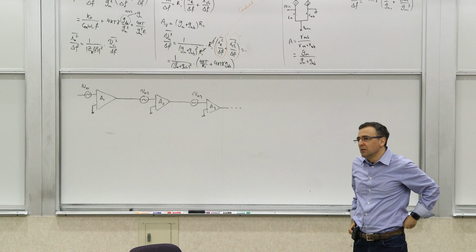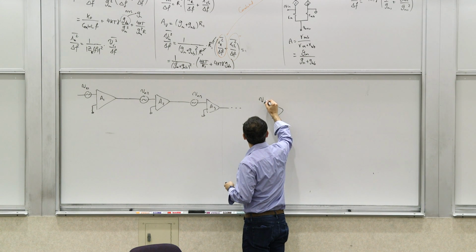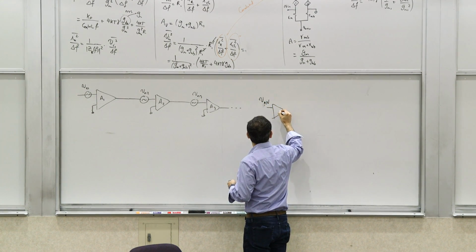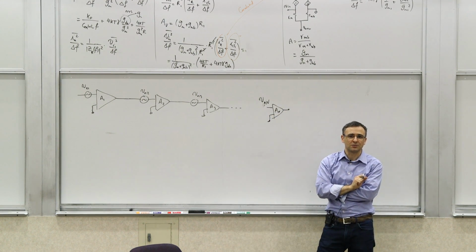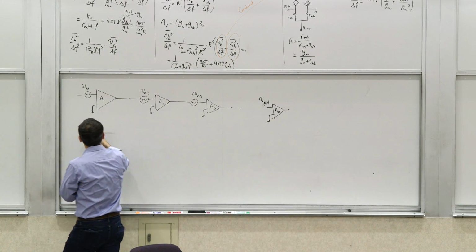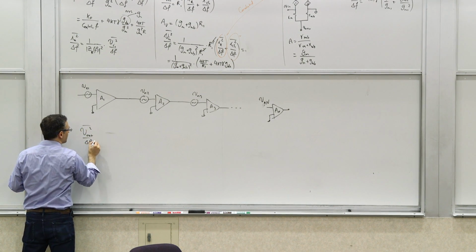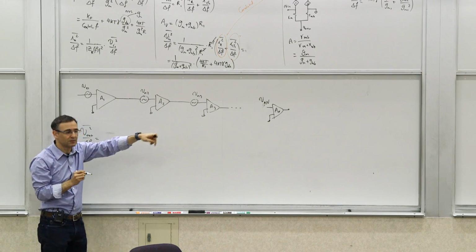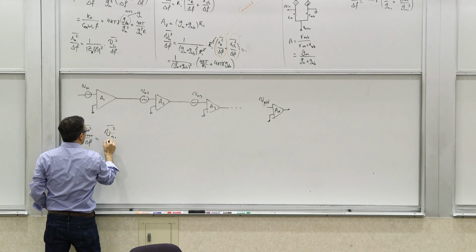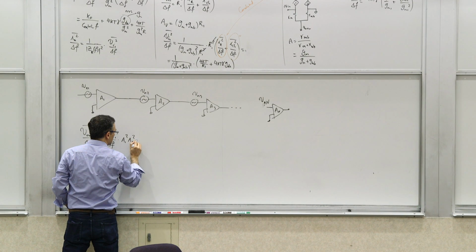So what is the input referred noise? Well, let's say you have n stages, Vn1, Vn2, ..., Vnn, with gains A1 through An. What is the total output noise? The output noise due to the first source, Vout squared over delta F, is going to be the power of this noise source times all of the gains squared. So it would be Vn1 squared over delta F times A1, A2, all of them squared, multiplied to An.